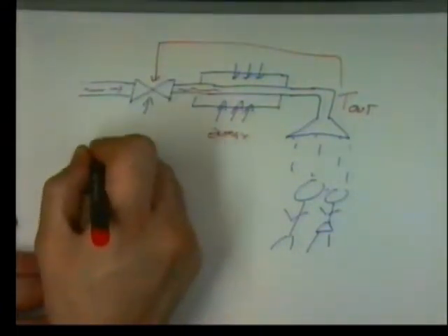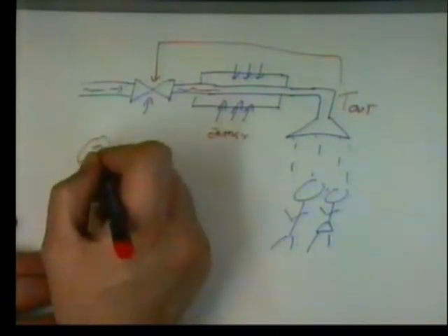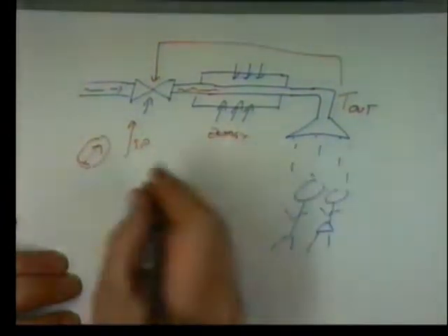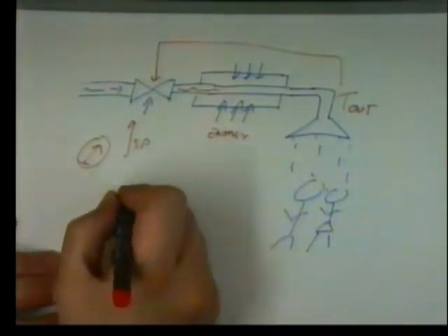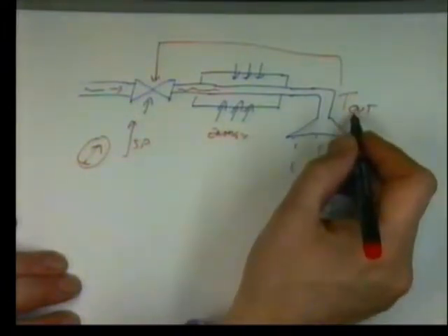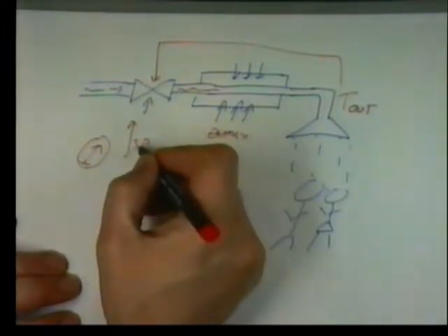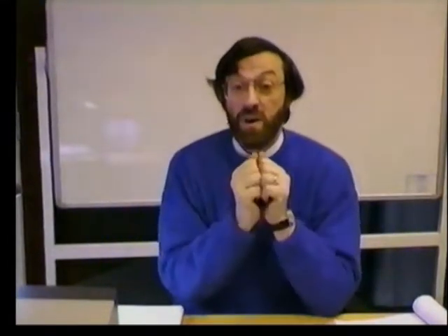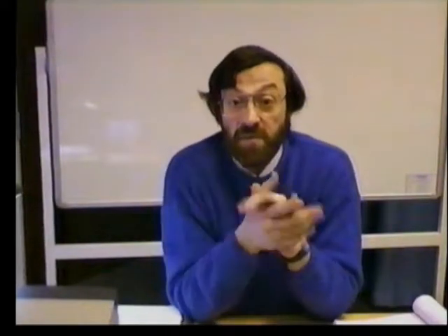Somewhere or other there'd be a little dial where you choose the temperature you want. That's your set point. And so we have a very simple control strategy: we have an error, the output temperature minus the set point, and that tells us the position of the valve. The greater the error, the more we would close the valve off to make the water hotter. It would work. There's nothing wrong with feedback control for a shower, apart from one thing.